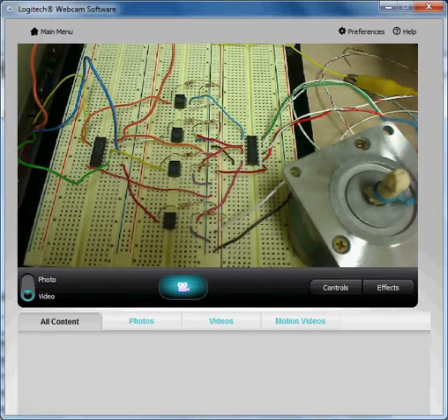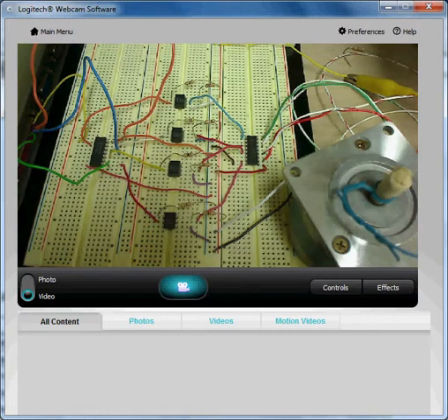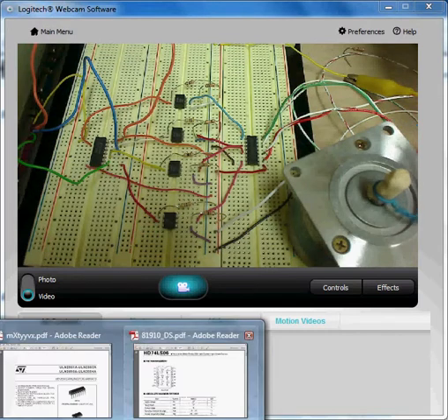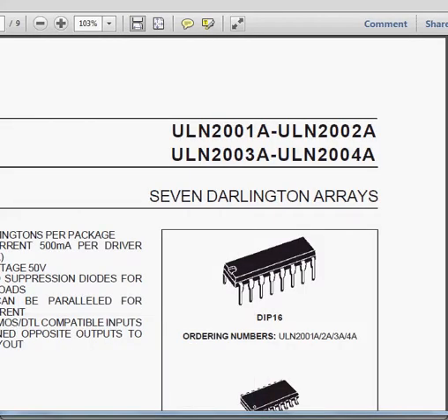After the 4N26, the sequence code will be applied to this ULN2003. ULN2003, in fact, is 7 Darlington arrays. Last class, when we built the driver, we used a Darlington pair. So if you want, you can also use Darlington pairs. Then here you need 4 Darlington pairs.